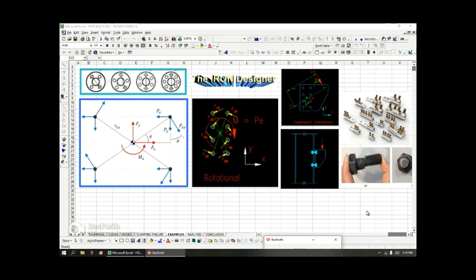To the right, you have some designs there where you put the rods inside those parts and tighten down the screws, and then those rods are in tension. So the bolts are in shear when the rod is inserted, and then you have the yokes, which are bolted down or attached a different way. So that's a product, some kind of a shear bolting product, maybe for fast assembly out in the field without welding or having to drill all the way through. They're just relying only on the pressure applied by the bolt creating shear.